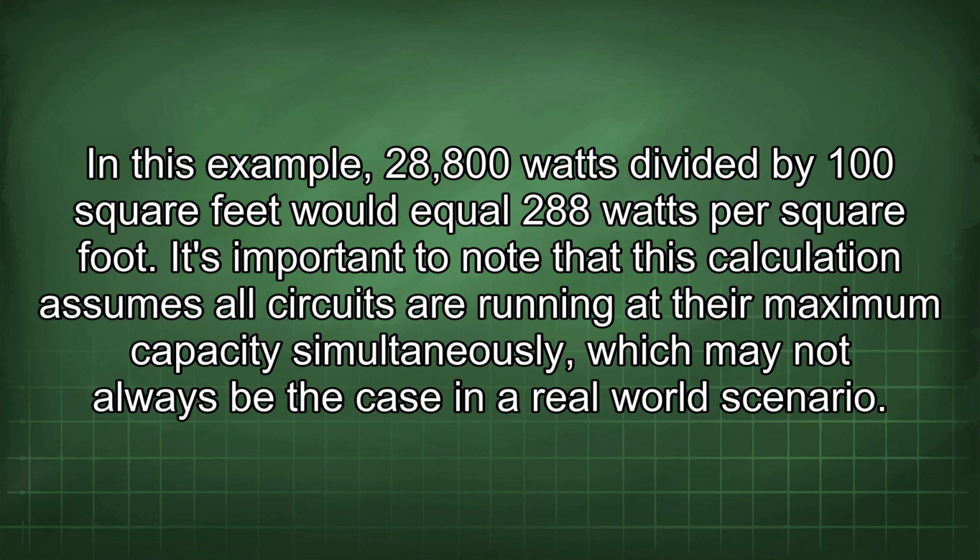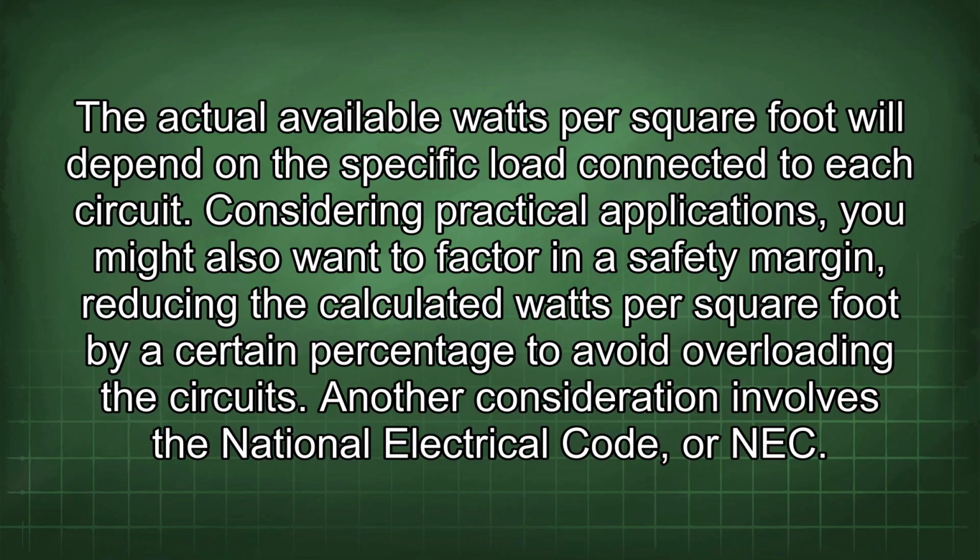It's important to note that this calculation assumes all circuits are running at their maximum capacity simultaneously, which may not always be the case in a real-world scenario. The actual available watts per square foot will depend on the specific load connected to each circuit. Considering practical applications, you might also want to factor in a safety margin, reducing the calculated watts per square foot by a certain percentage to avoid overloading the circuits.